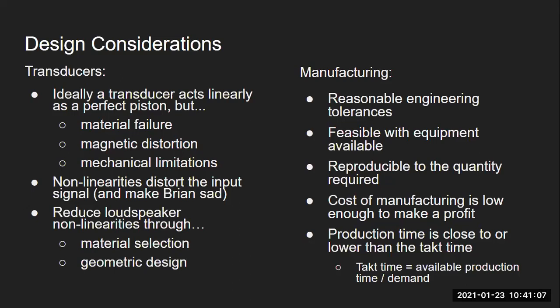of acceleration. If you've got your cone and it's got a certain mass and a certain stiffness to it, you're moving it back and forth quite quickly, especially in those upper frequency ranges. If you think about 20 kilohertz, that's moving back and forth 20,000 times in 1 second. So the acceleration that a cone sees is well over 200 Gs at those frequencies. It's something I always like to brag about whenever I talk to Air Force or NASA engineers.